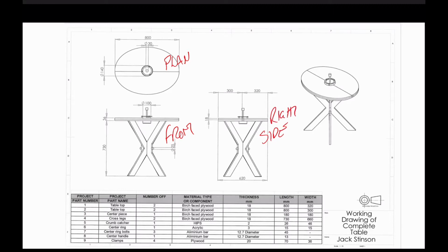and it's a side view from the right hand side. Okay, down in the right hand corner then this little logo, so that little logo must be there. That's third angle projection, and that's telling the person who's looking at your drawing that you have got those three views in those three positions. And here of course then, as I said, we've got a 3D view. So that's initially what the drawing layout should look like.